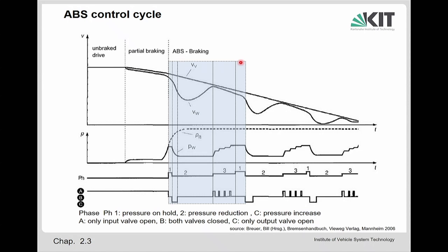So this will reduce the maximum force which is transmitted, yes, but it avoids that the car starts to rotate around the vertical axis. And so the driver can feel, I'm braking, and now I have a steering tendency of the vehicle, and I can use my steering wheel to work against that.